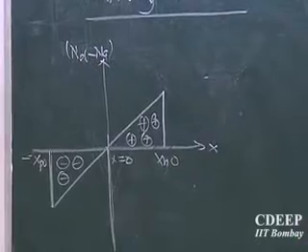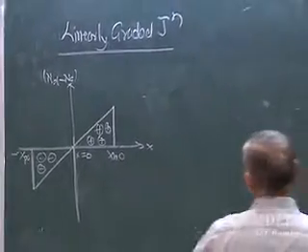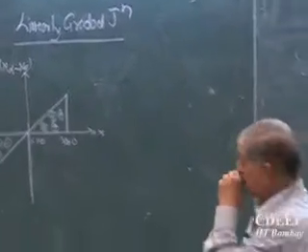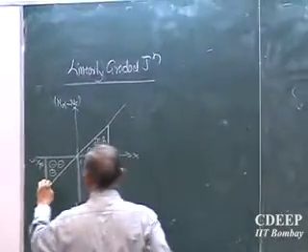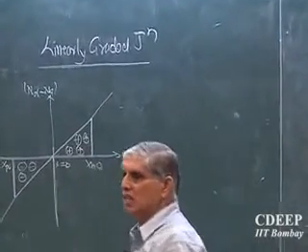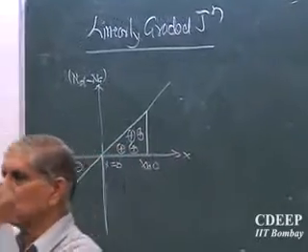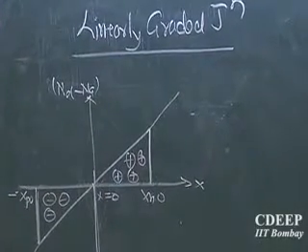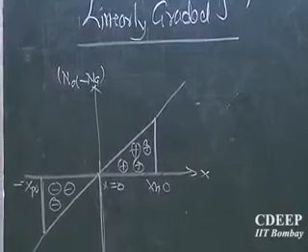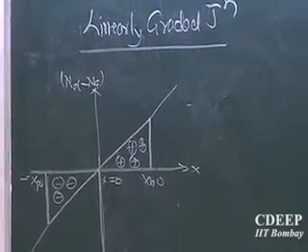So what should I write? Yes? No, this will continue. Yeah. The profile is there, but only these many are essentially exposed because of the concentrations, which give whatever slope you are giving. Only these, like in a normal step junction, only a certain amount of ions will create some field. Once that field is reached, no more diffusion, so it will stop.